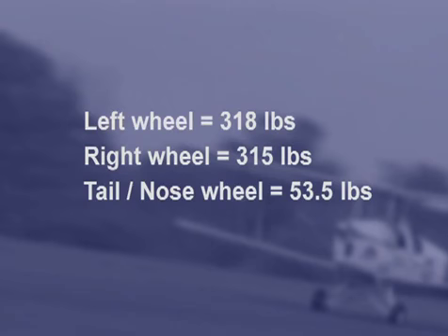Now, if there's a big weight change, like we've got, say, 20 pounds between one and the other, you might want to look for a reason why there is. Is it something that's been installed in the aircraft on one side, say, a wing tank on one side and not on the other? Or maybe be a little suspicious of your scale, that your scales are giving you a false reading. But it's not uncommon to have a few pounds difference between left or right.